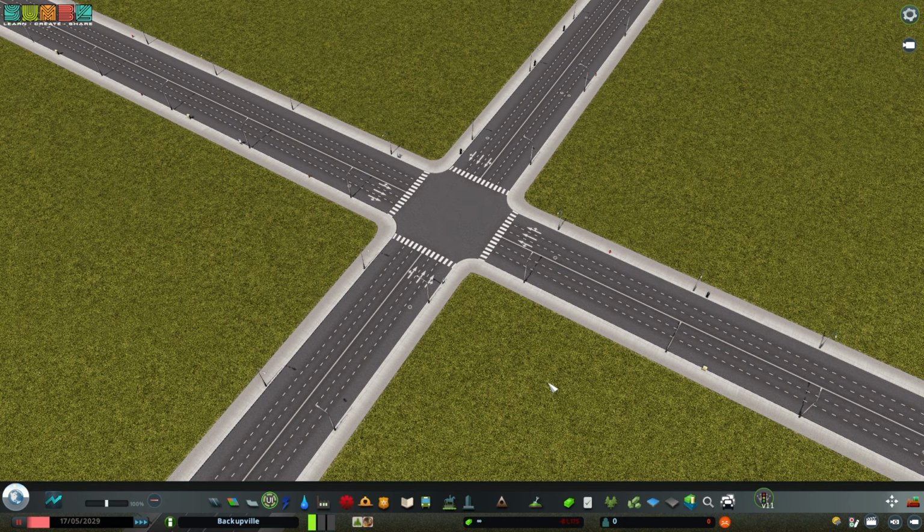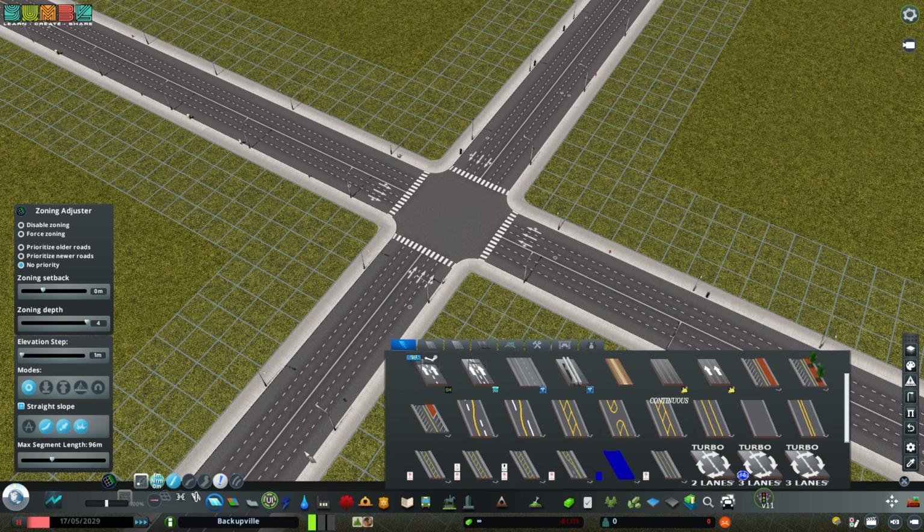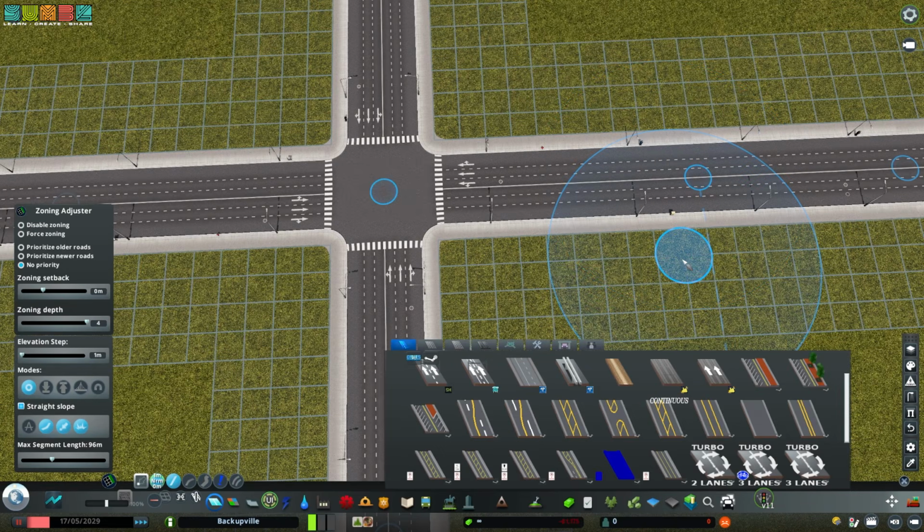This will be the location of our continuous flow intersection. The reason that cities go to this in real life would be for, let's say, a high-density intersection that's maybe on its way to becoming an interchange, or maybe there's not enough traffic to warrant an interchange yet, but you still need to solve the traffic problem that you have at hand. This is a very high-flow, at-grade intersection, so it doesn't require any overpasses, underpasses, or ramps. It's all at-grade. And it's rather technical compared to what I usually do, so I'm curious to see how this comes out with the finished product.